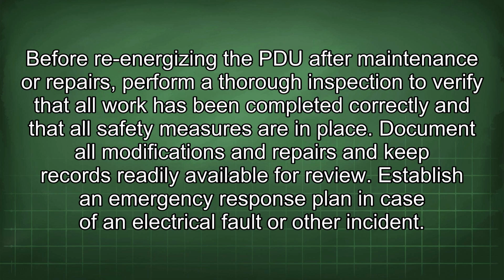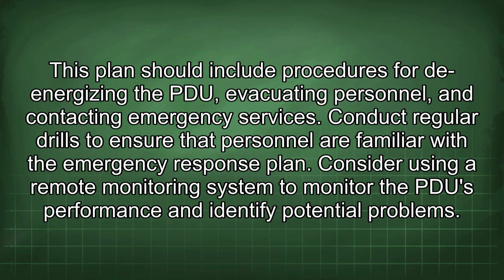Establish an emergency response plan in case of an electrical fault or other incident. This plan should include procedures for de-energizing the PDU, evacuating personnel, and contacting emergency services. Conduct regular drills to ensure that personnel are familiar with the emergency response plan.